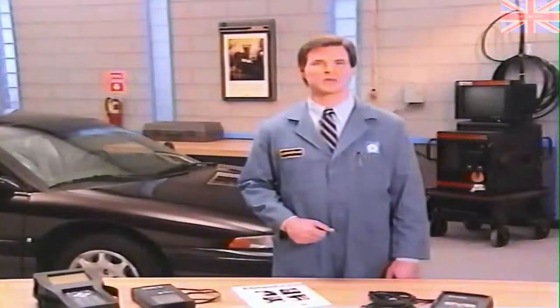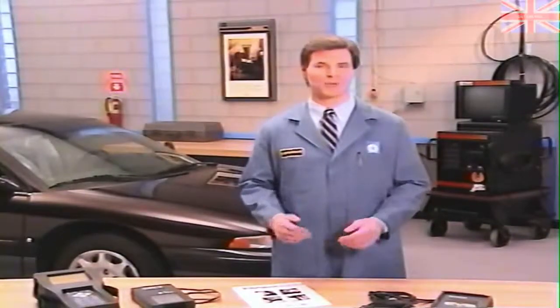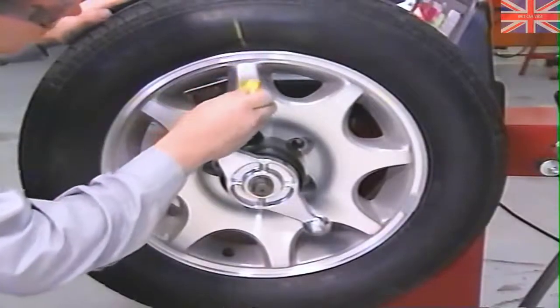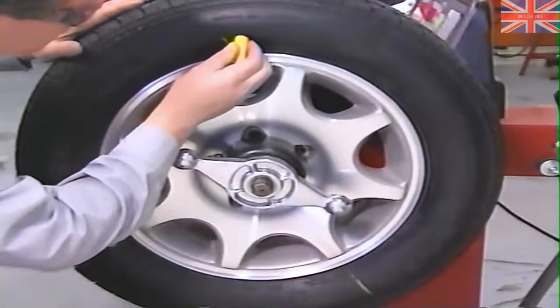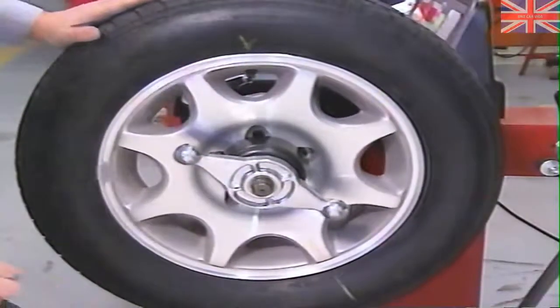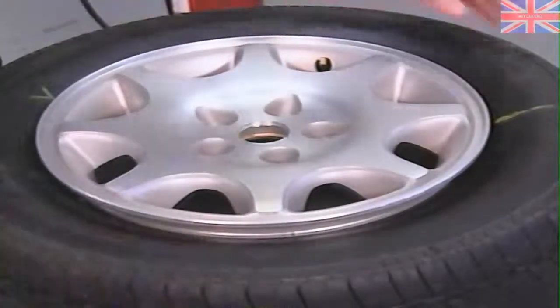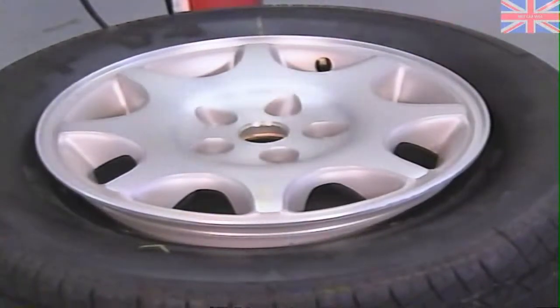Since the wheel assembly shows excessive radial runout, we need to determine if the runout exists in the tire, wheel, or a combination of both. To accomplish this, we'll use a procedure called match mounting. First, we'll mark the location of the high spot on the tire and the wheel. Then we'll place a mark on the tire sidewall at the location of the valve stem. This will be referred to as the 12 o'clock position. After breaking down the bead, we rotate the tire 180 degrees on the rim so the valve stem reference mark is now at 6 o'clock.